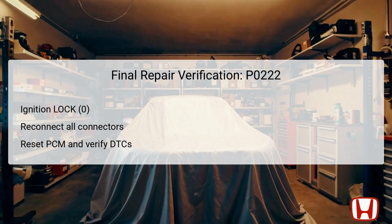Final repair verification for DTC P0222 involves several confirmatory steps. First, turn the ignition switch to lock 0 and reconnect all connectors that were previously disconnected during the troubleshooting process. After confirming connections, exit the SCS mode on the HDS tool to restore normal vehicle operation.